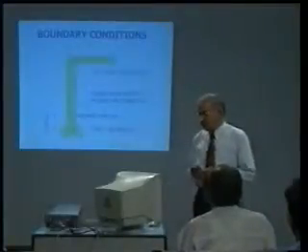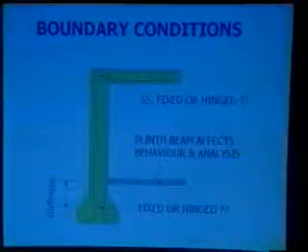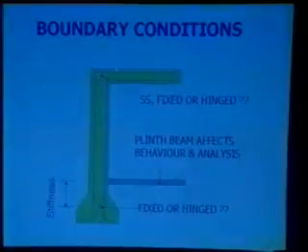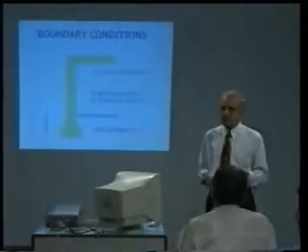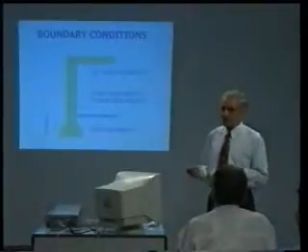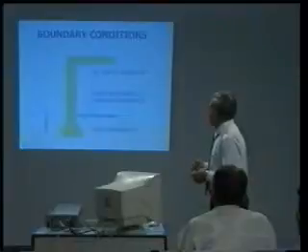Now, coming to the problem of boundary conditions. Now, at this place, if this bar and this bar are just left like this, or if this bar is taken inside and this bar is taken inside, it makes all the difference, whether it is a fixed condition or a simply supported condition. In RCC structures, gentlemen, a truly simply supported condition cannot be arrived at. So, you have to consider the question of partial fixity.